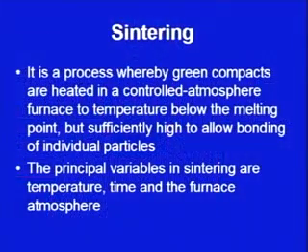Now, coming on to the basic concept of sintering. Sintering is a process whereby green compacts which have been obtained after the process of compaction are heated in a controlled atmosphere to a temperature below the melting point, but sufficiently high to allow bonding of individual particles. As we have been discussing in the last two lectures also, the temperature for sintering is less than the melting point of the metal. Suppose we are making use of titanium or tantalum or any other metal powder. So, the sintering temperature for that metal powder will be less than the melting point of the metal.